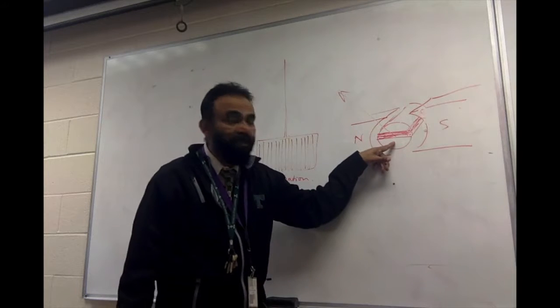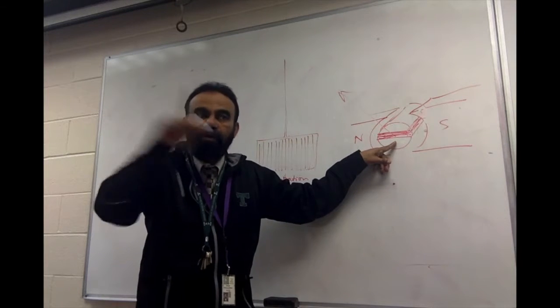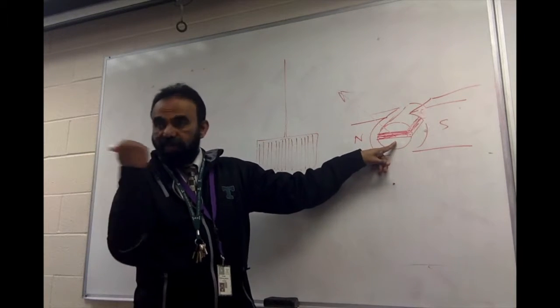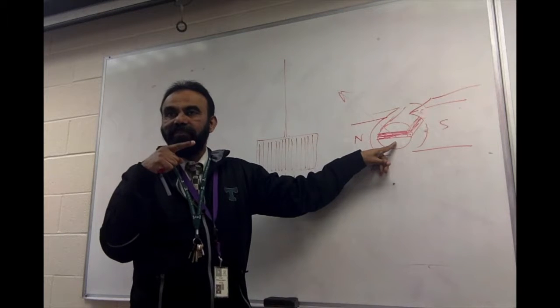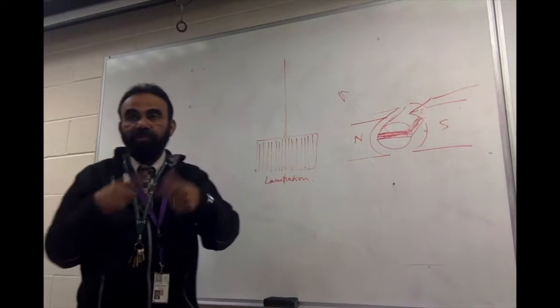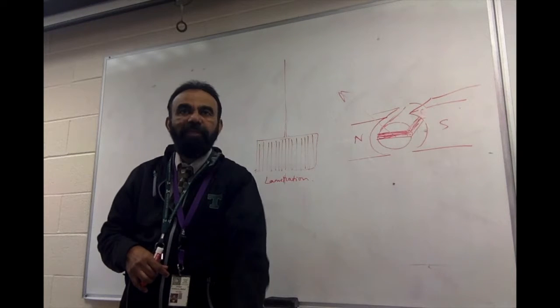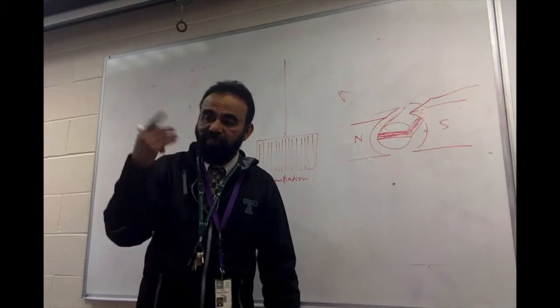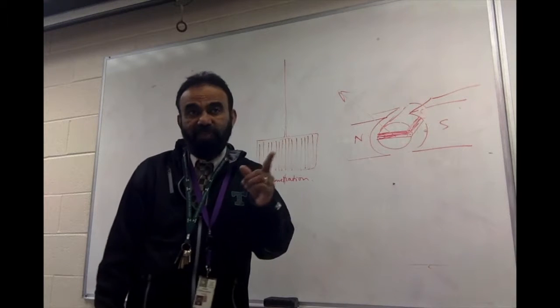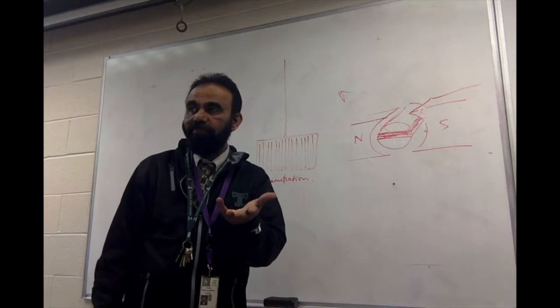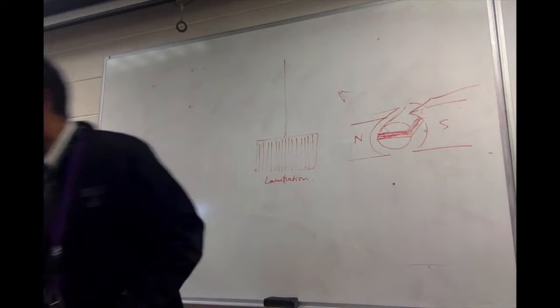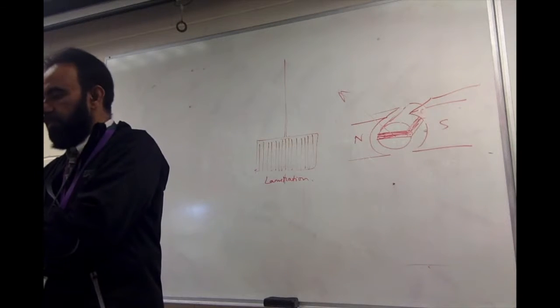So here we are deliberately keeping it as a solid core, not laminating it, because we want eddy currents to help us. But here in a motor, we don't want the eddy currents, and so we laminate it. So wherever we don't want the eddy currents, we laminate it. The same way as a transformer core. Did I say about the transformers? Yeah. So in a transformer core, I think I passed this around.